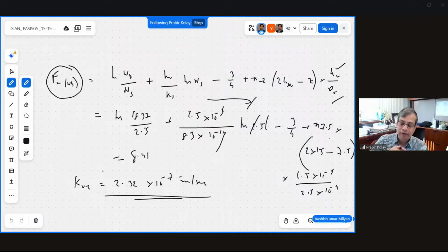Because horizontal and vertical permeability is changed, basically you need to use this equation. The mid depth of the soil layer. So how much is this? So basically FMND we calculate at the mid depth, right? So that's why we use that. The Z over here is 7.5. Okay? So total is 15 meter long. So this is 7.5 mid depth. Okay. So now the last problem is,